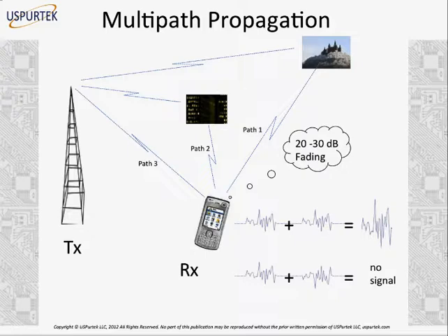Your signal fades ultimately. So this is a known problem, a nuisance sometimes. We are in some important call, and because of this multipath propagation, different signals cancel out each other or add to each other in a random fashion, and they lead to multipath fading.